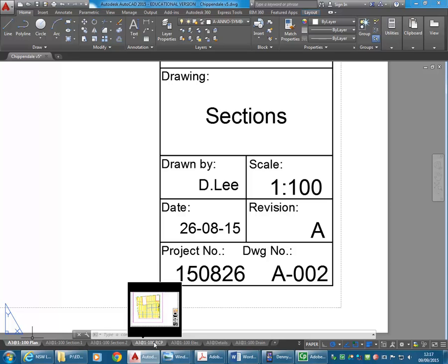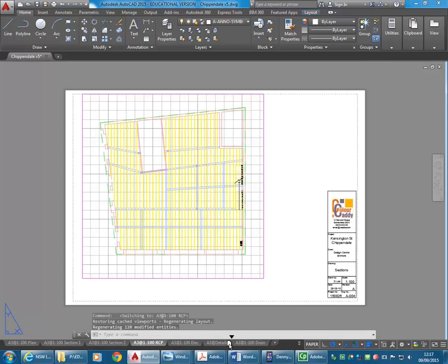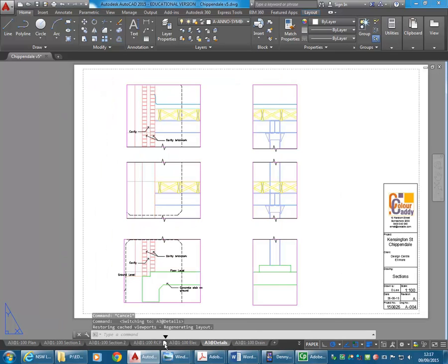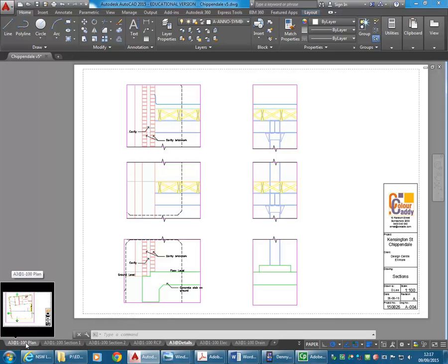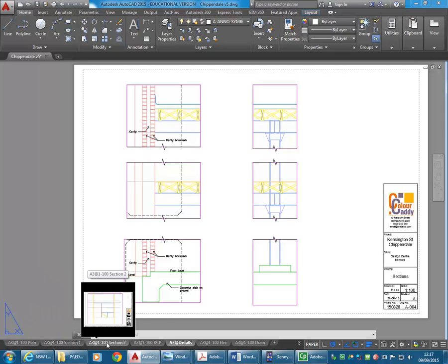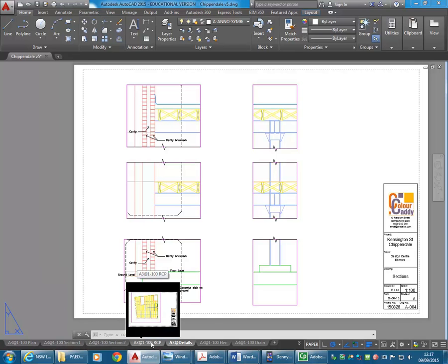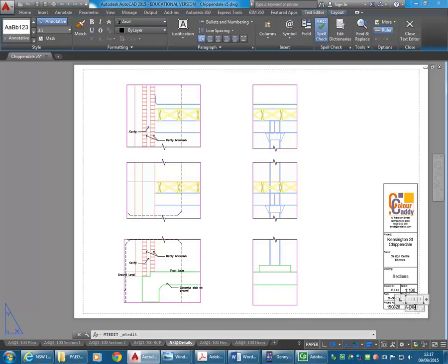Yeah, so the reflected ceiling plan, that really should have come up to the floor plan, but since I didn't, we can put that after the details, or after the, no, maybe not after the details, maybe just after the elevations. The order's really up to you, but there is a bit of a convention there. So plans, then sections, then elevations is a good way of ordering them. So we're going to have plans is number 2, sections 3 and 4, elevations 5 and 6, and then the RCP 7, and details will be sheet 8.